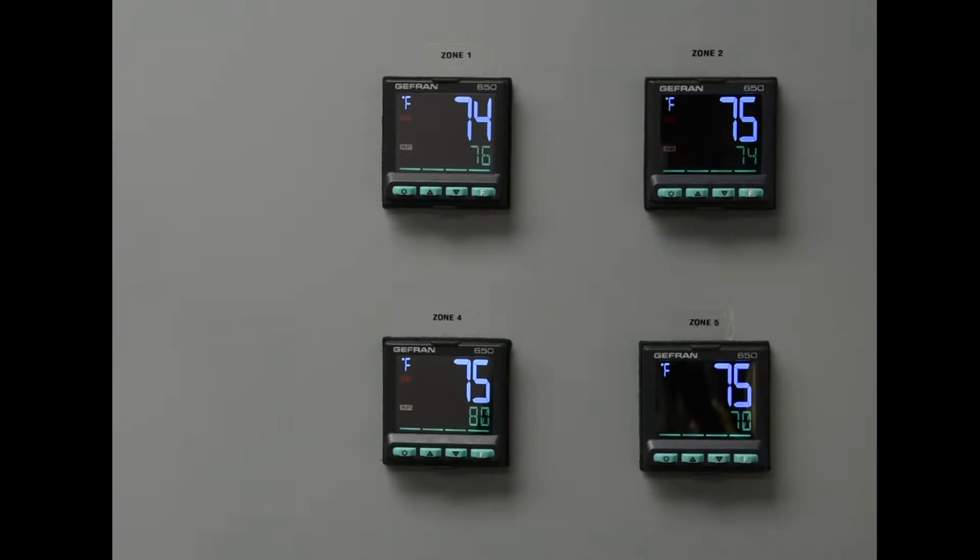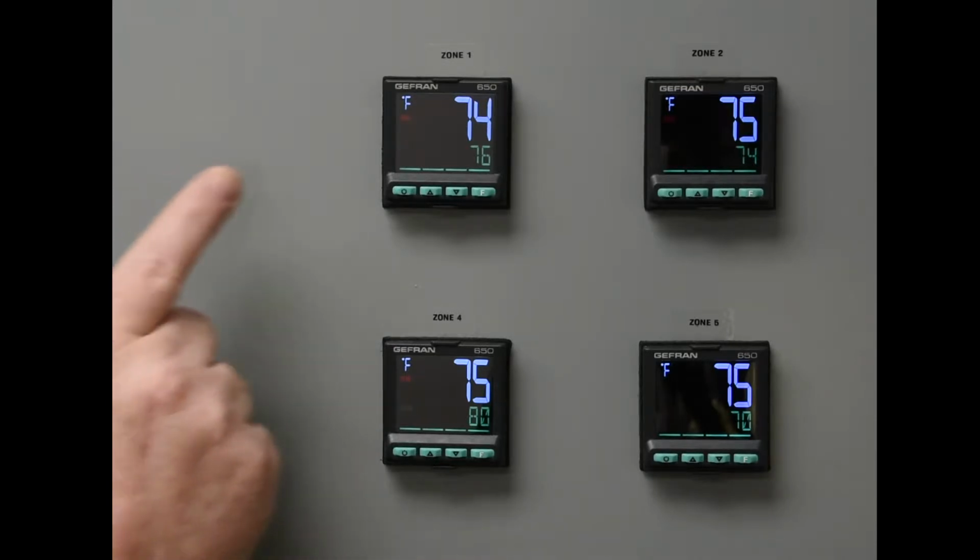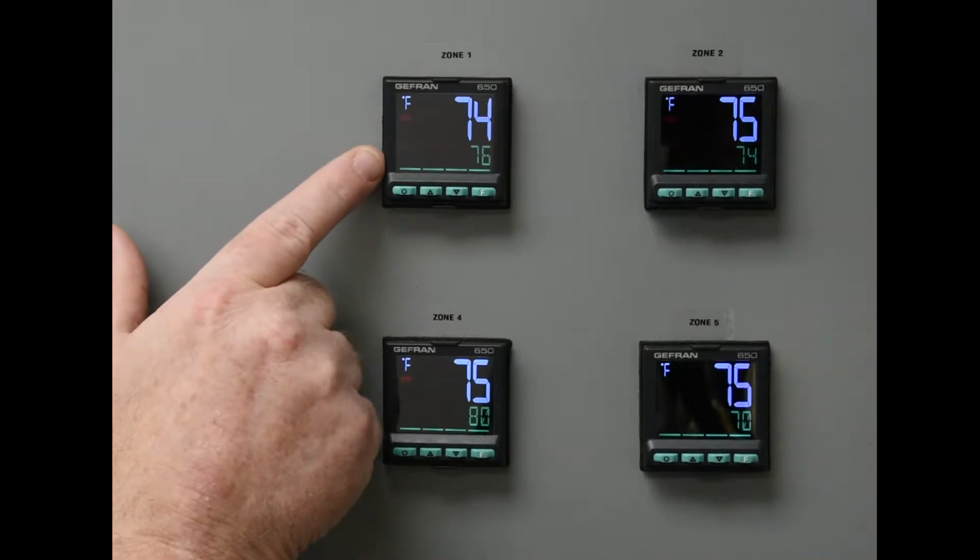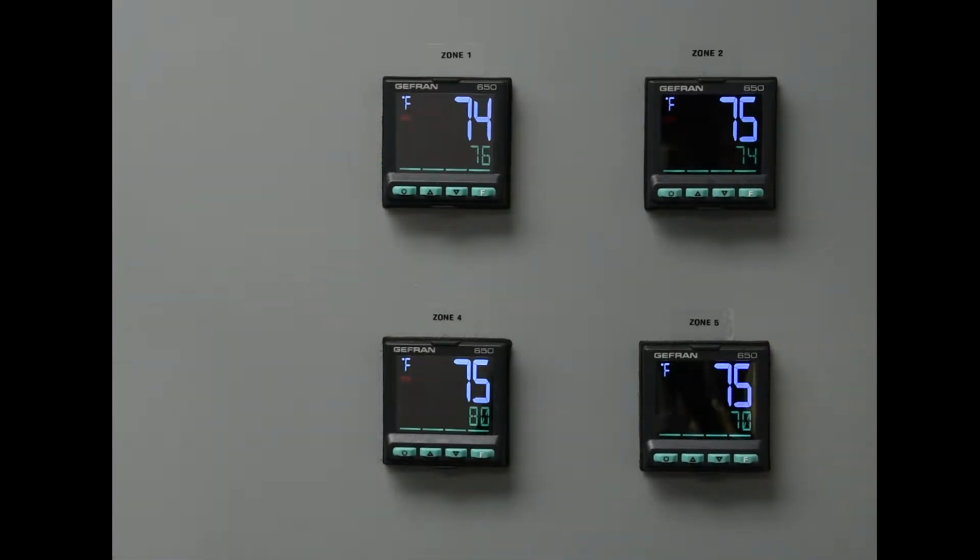You will see RUN, which is the set point program is active, something resembling a hockey stick to say that the program is in a set point ramp. TUN, which means the PID parameter is in the auto tuning active mode. MAN, to show that the controller is providing power either based on a manual setting or automatic based on the temperature set point.